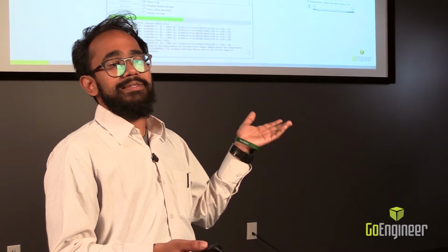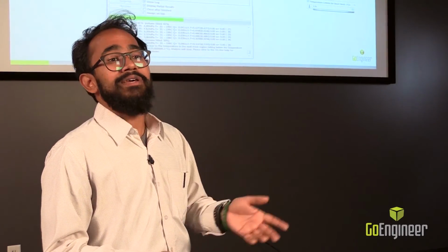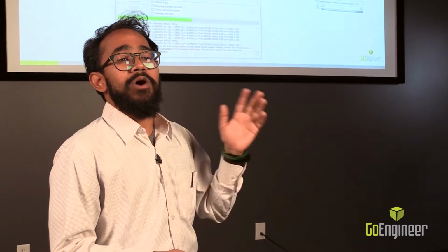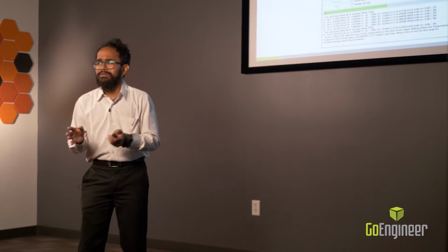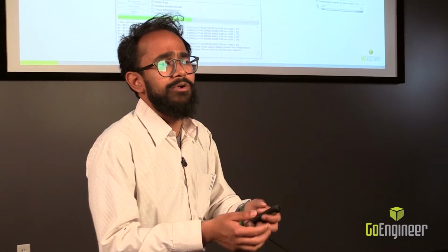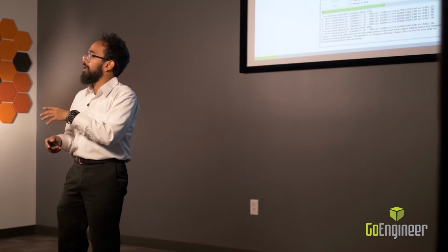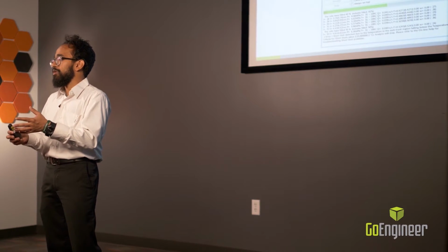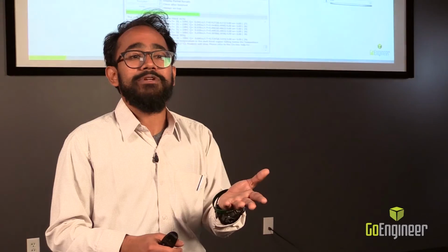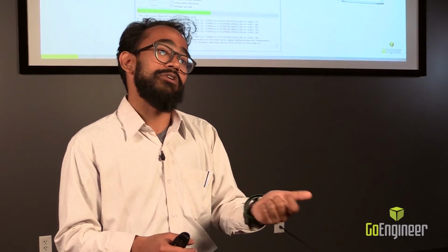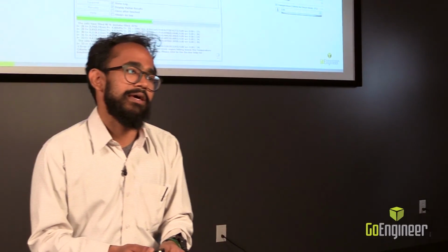Now, finally, and this is one of the best improvements we've had in the Plastics analysis tool, is our ability to predict short shots that include temperature profiles. So up to 2017, short shots in the cavity were only predicted due to a lack of enough injection pressure. But right now, we can actually study the temperature profile of the component during the injection molding process and predict if that temperature profile would cause premature gate freeze or premature plastic freeze, that would essentially lead to short shotting of the plastic inside the injection mold.